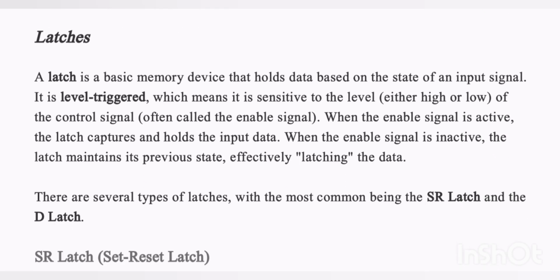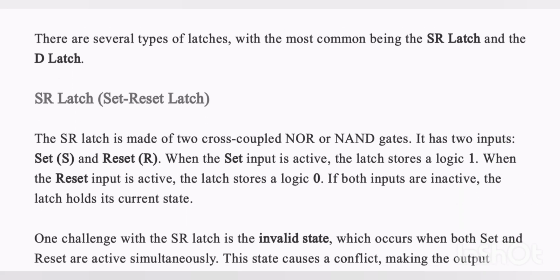Latches. A latch is a basic memory device that holds data based on the state of an input signal. It is level triggered, which means it is sensitive to the level, either high or low, of the control signal, often called the enable signal. When the enable signal is active, the latch captures and holds the input data. When the enable signal is inactive, the latch maintains its previous state, effectively latching the data. There are several types of latches, with the most common being the SR latch and the D latch.